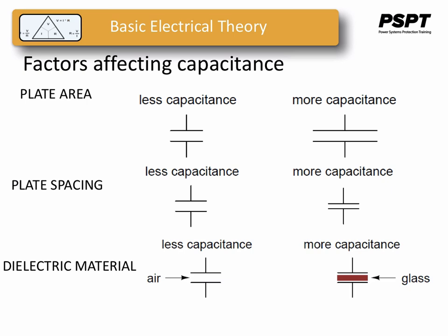The greater the number, the greater the permittivity of the material. Glass, for instance, with a relative permittivity of 7 has 7 times the permittivity of a pure vacuum, while air has almost the same permittivity of a pure vacuum and consequently will allow for the establishment of an electric field flux about the same as that of a vacuum, all other factors being equal.